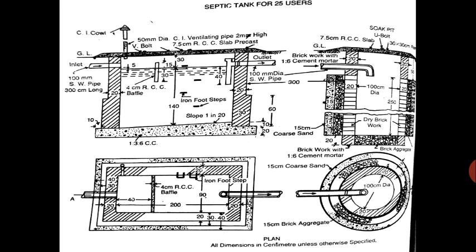And the soak pit also consists of 1:6 cement mortar for the foundation, and they have used 1:6 cement mortar for the brickwork also.